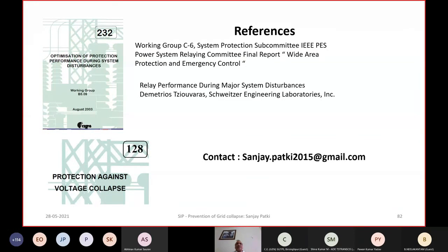The second question you said, in terms of current sensitivity, again the same thing. It's a compromise between how sensitive you want to keep the protection, which also decides the coverage, how much winding will get protected. I think near the neutral we need not be too much worried. So even if you are normally restricted, we expect at least 85% of the winding to be protected. If you are ensuring that much coverage, a slightly higher milliamp setting is okay.